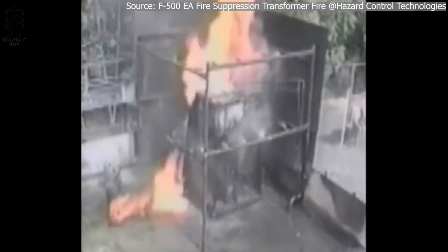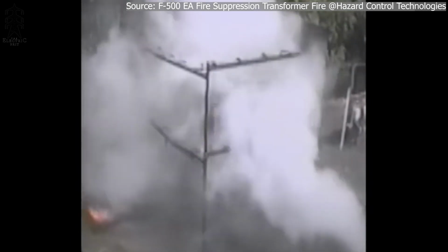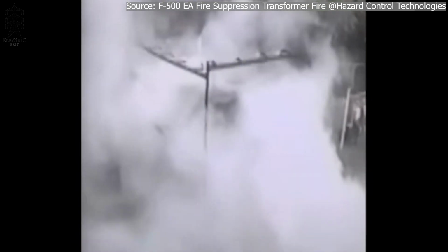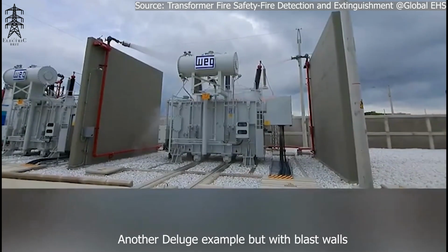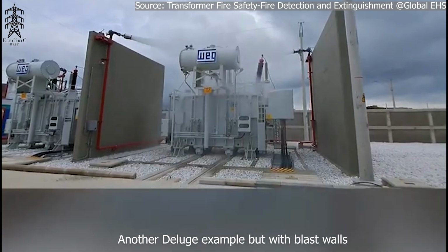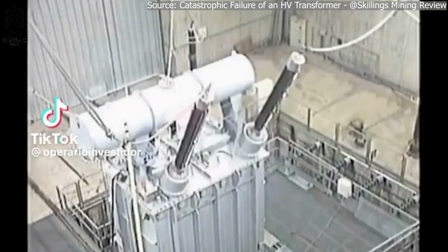If two transformers are right beside each other, there might be a fire deluge system in place to minimise the spread of fire if one were to happen if the tank ruptures, and if not, then a blast wall is typically built from brick, concrete or metals to reduce the spread of fire if a fault occurs. So now you know all the basics about transformers. How do they break?